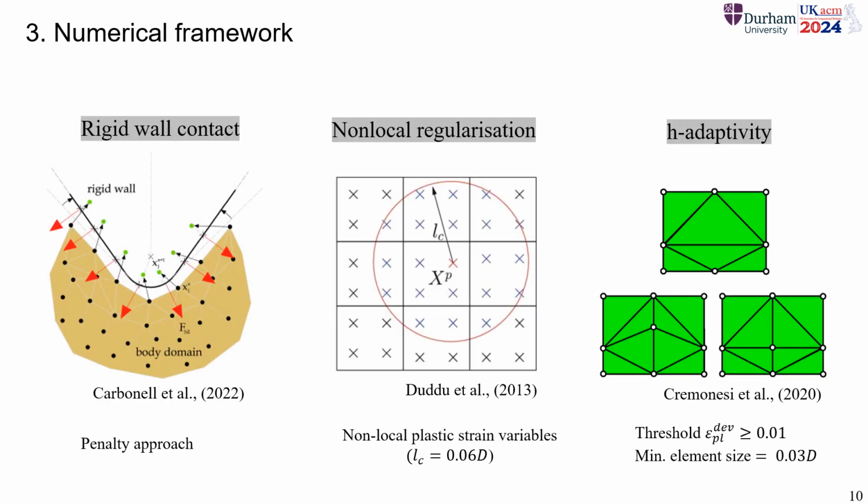Then this approach is also further enriched by considering contacts between the wall and the mesh. In this case, we're using a rigid wall, meaning the shape of the wall is approximated with a function, making it very easy to detect contacts. If you evaluate a function for each node position, depending on whether the value is greater than 0 or less than 0, you get whether a point is inside the wall, and then if it's inside, you just apply a repulsive force depending on the distance from the surface to the mesh.